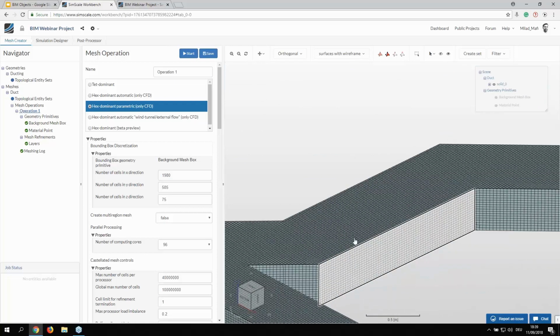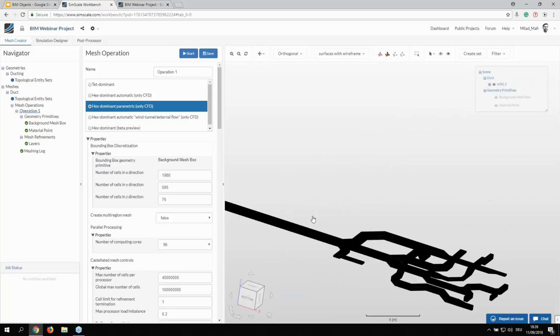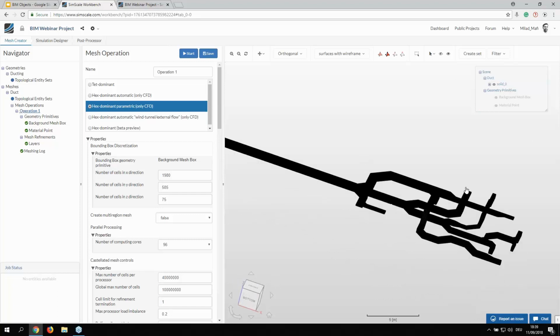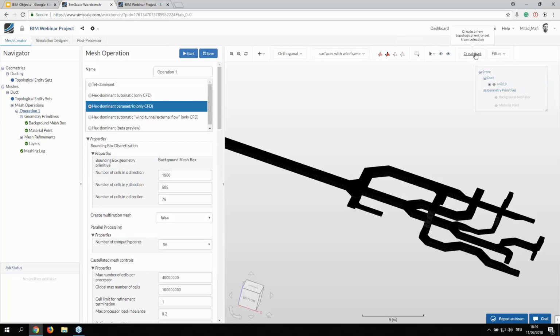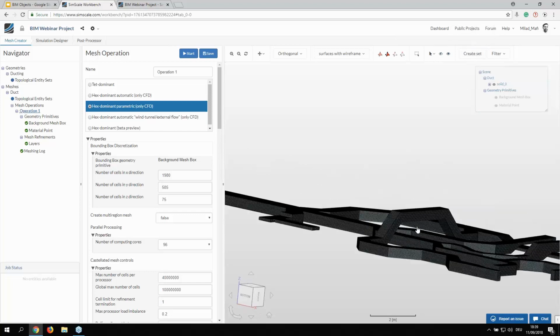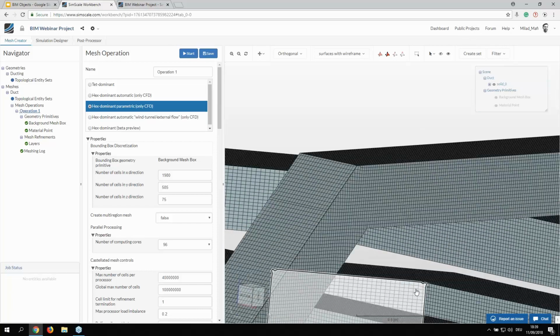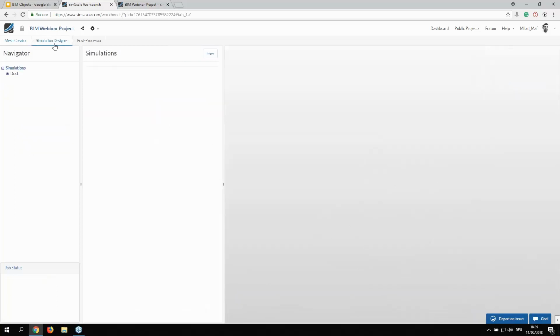And for the center of each of the cells, we are calculating velocity and pressure values. And for sure, you need to adapt the mesh fineness and make it very fine where you expect to have large gradients and large changes, and make it coarser where you don't think that we have large gradients. And yeah, we can really see how, for example, near edges, the mesh is refined automatically.